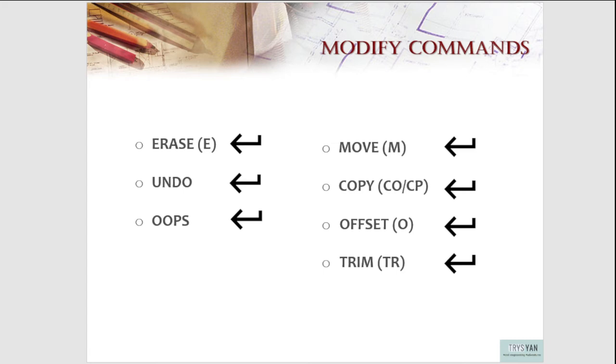Okay. So if I want to trim this part only, no? 1, 2, 3, 4. These 4 lines in the middle of this line, 2 lines, no? 1, 2, 3, 4. So itong line na to. Yun lang yung ititrim natin. So pwedeng-pwede siya. Just type TR, the shortcut for trim, then enter. You can also press another enter or space bar. Kasi pwede rin yung right click, no? Pwede rin space bar. Ayan.